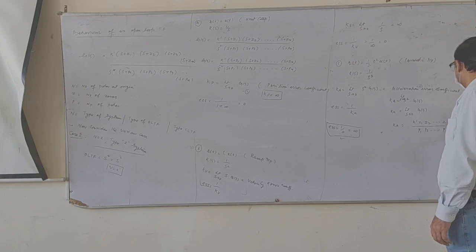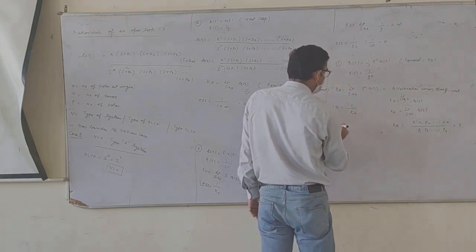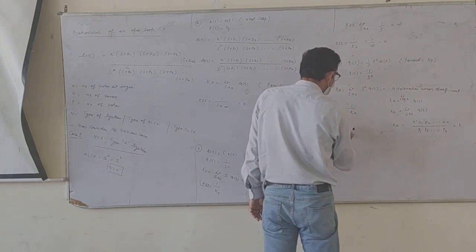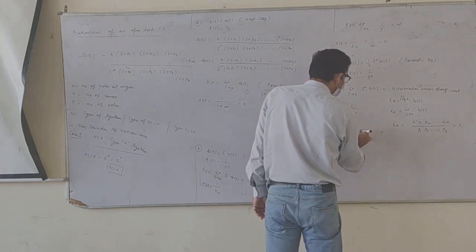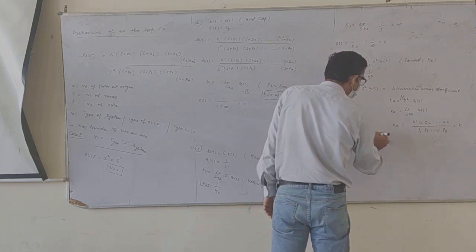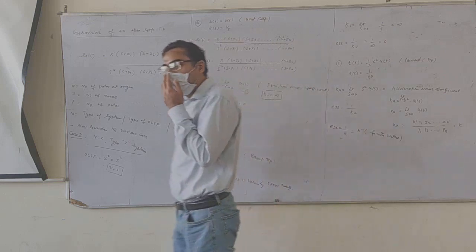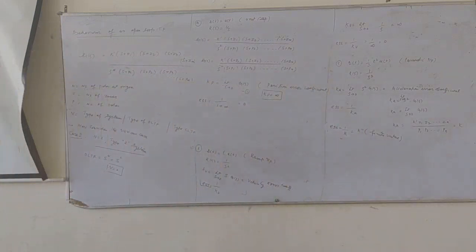Let us say this is a constant K. If this is a constant K, then steady state error will be 1 by K. It's again something like constant K double dash, whatever you see. So this is again a finite value. So it should be very clear that whenever the input is unit parabola and the system is type 2 system, only then are we going to get a finite value in type 2.